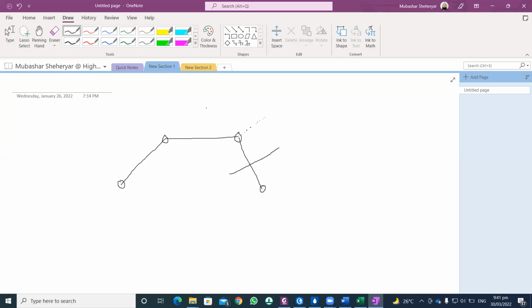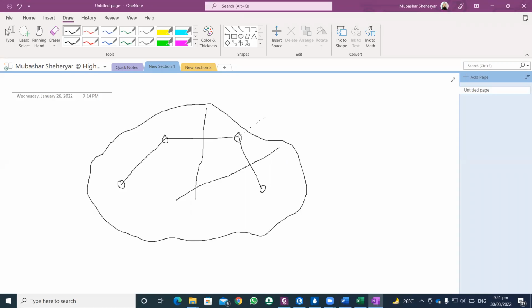Similarly, drawing a perpendicular here, and assuming, for example, the boundary polygon is here, up to that, this area is the polygon for that node. Similarly, the perpendiculars are drawn by WaterGEMS or the GIS to this pipe.